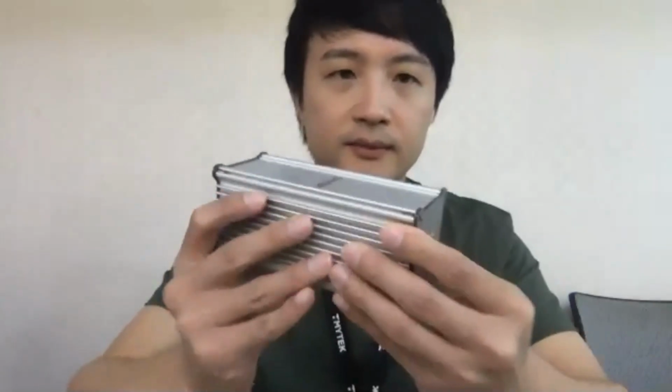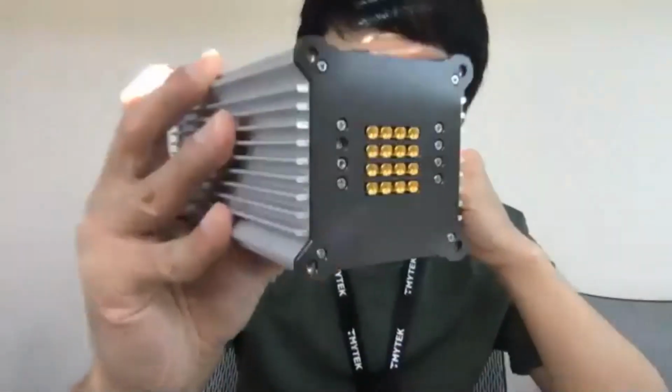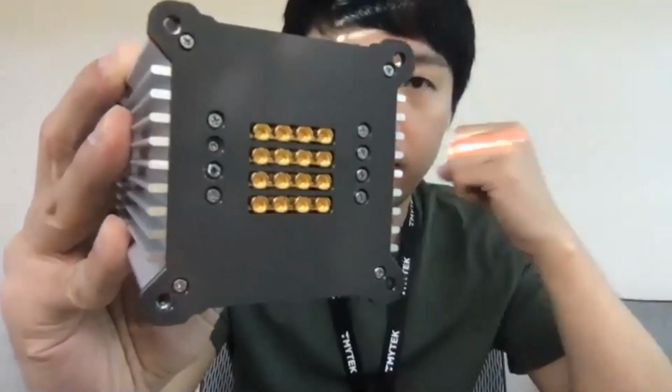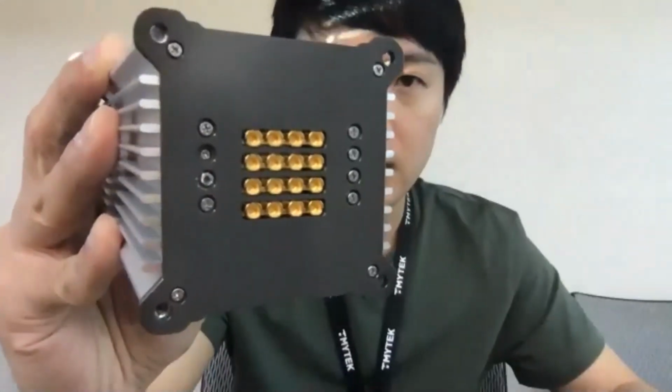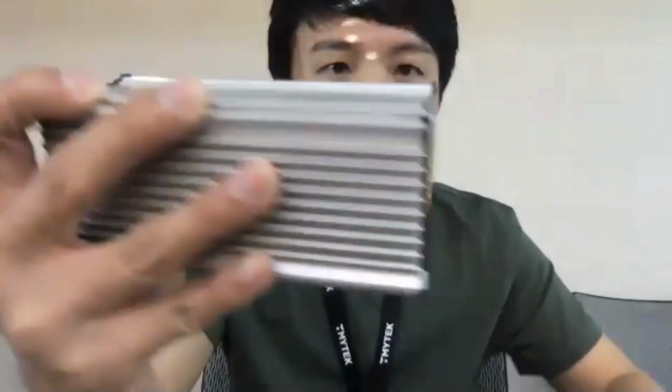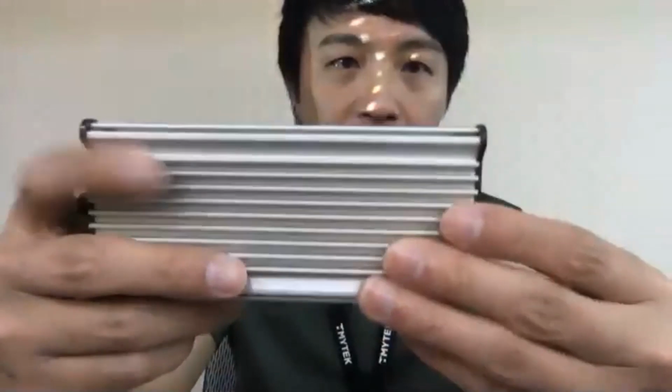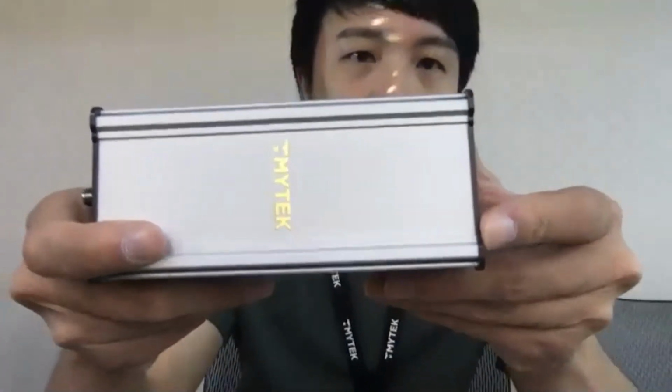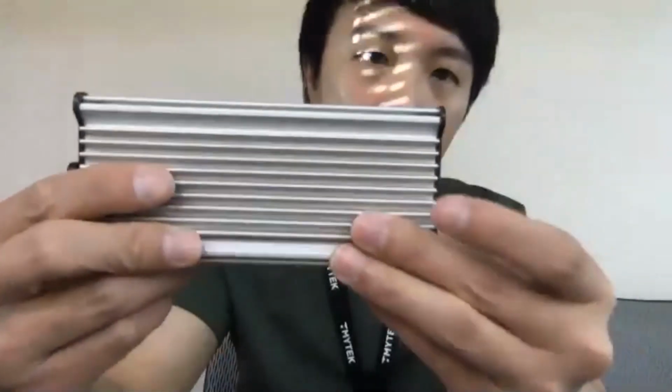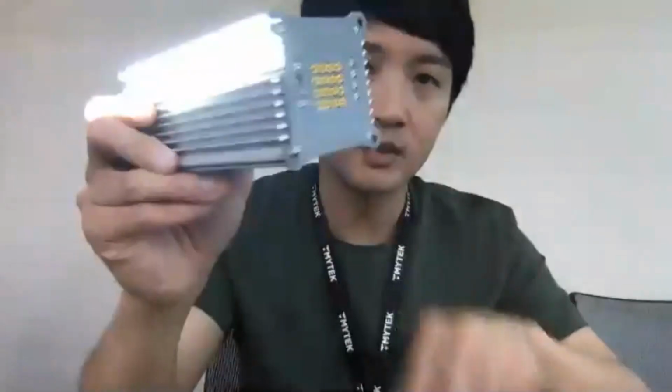And fortunately, we found that a standard SMPM connector can be the solution. And that's what comes up as what we have today. That's the BBox, as you can see here. They are 4x4 SMPM connectors, and all the amplifier and beamformer functionality were located in this small silver box.